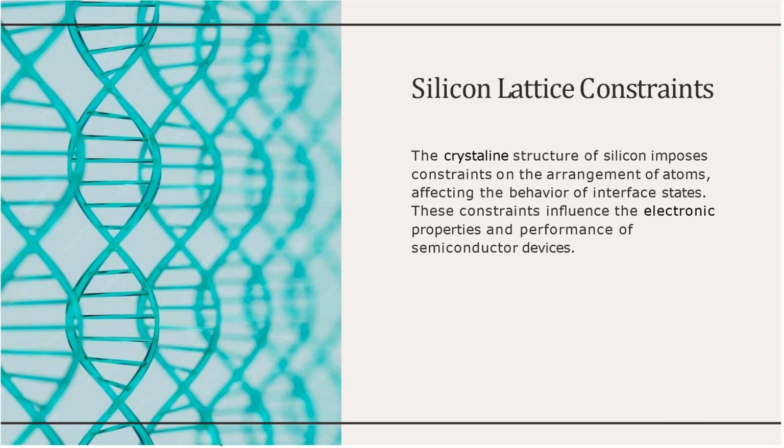The incorporation of dopants or impurities in the silicon lattice, which can alter the electrical properties of the material depending on the size and valency of the dopant atom. It can either substitute for a silicon atom in the lattice (substitutional) or occupy an interstitial site between silicon atoms (interstitial). Substitutional dopants tend to cause less strain than interstitial dopants, but they also have lower diffusion coefficients.